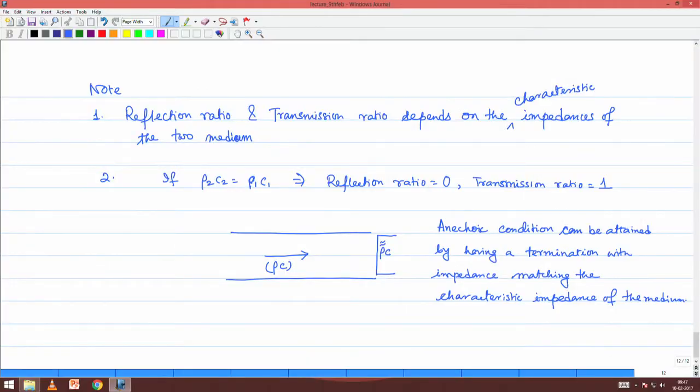If we do see that the impedance across the frequencies of interest is falling near about the characteristic impedance, then we will believe that it is doing a reasonable job. Otherwise, we will have to rework these calculations.